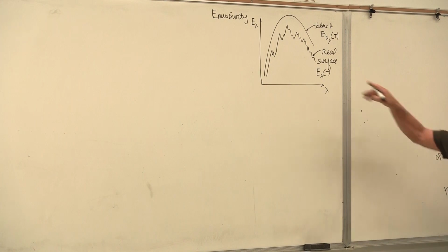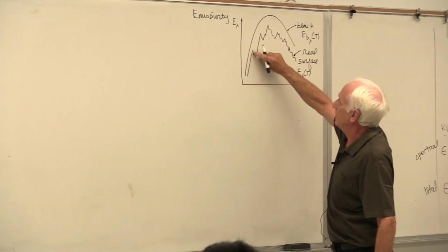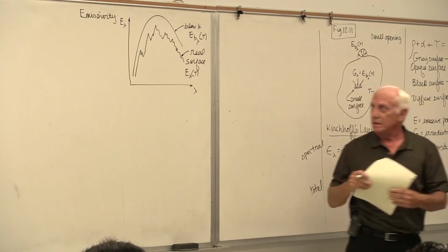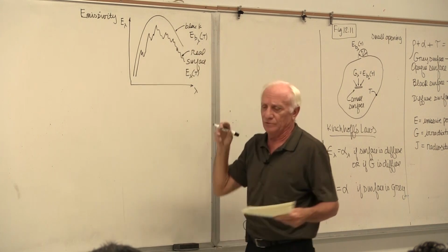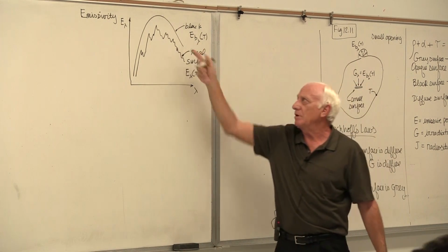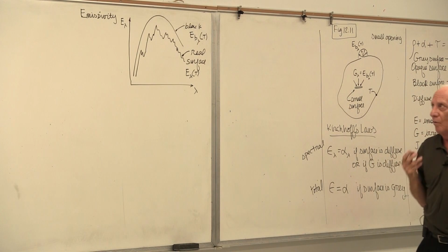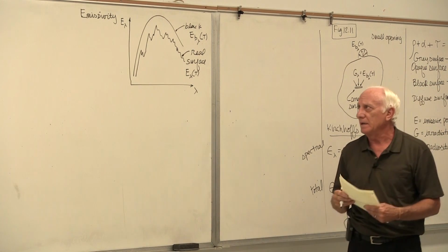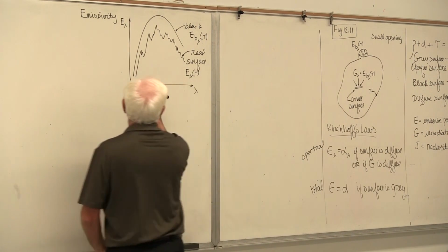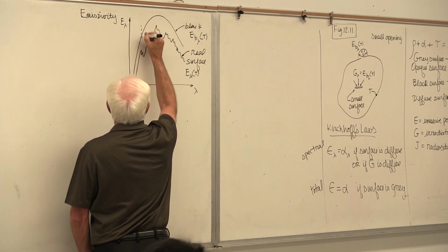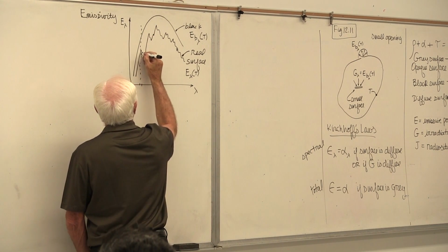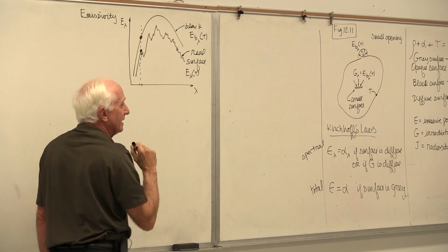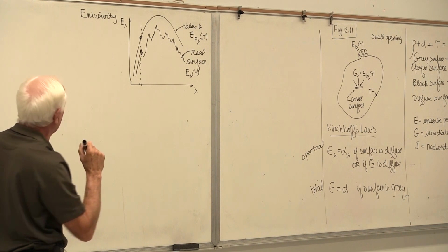The emissive power of that gray paint here. If we figure out what the black body emissive power would be, it would be this line here. At what temperature? Room temperature, 300 K. One's a black body at 300 K, the other is the real gray paint at 300 K. At any particular wavelength, if we divide the real by the black body, that's the definition of spectral emissivity.